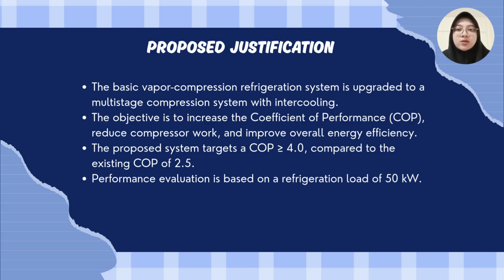For proposed justification. 1. The basic vapor compression refrigeration system is upgraded to a multi-stage compression system with intercooling. 2. The objective is to increase the coefficient of performance COP, reduce compressor work, and improve overall energy efficiency. 3. The proposed system targets a COP higher than 4.0 compared to the existing COP of 2.5. Lastly, performance evaluation is based on a refrigeration load of 50 kilowatt.